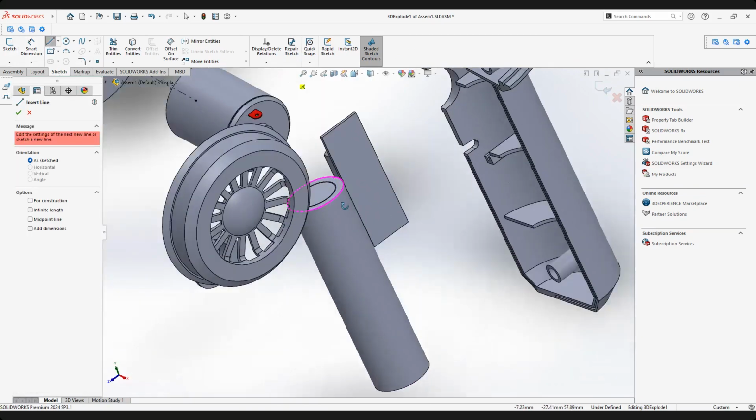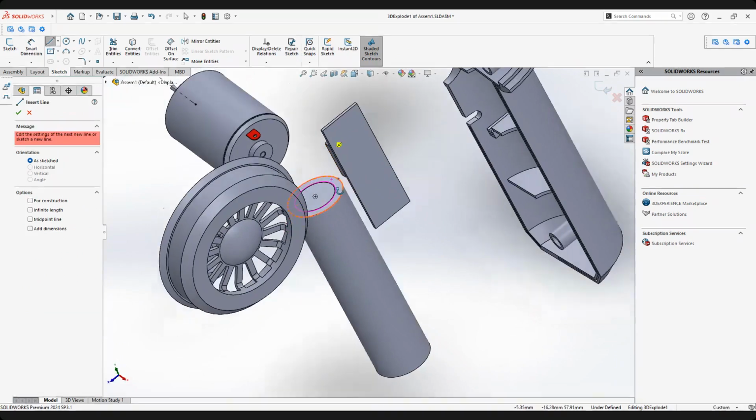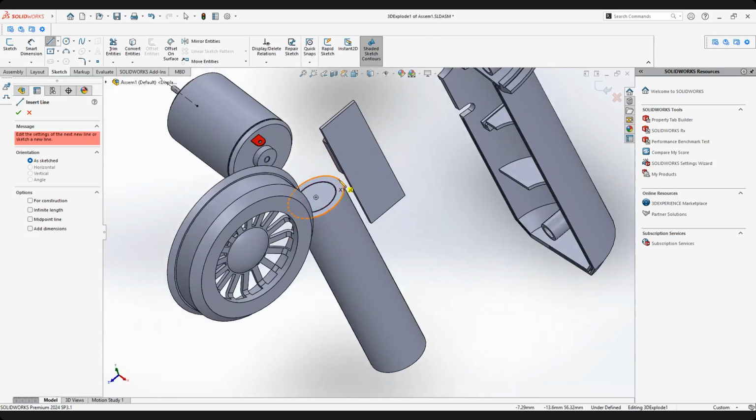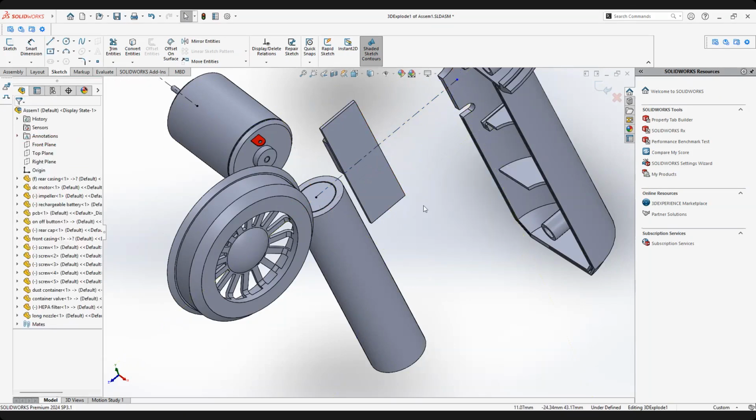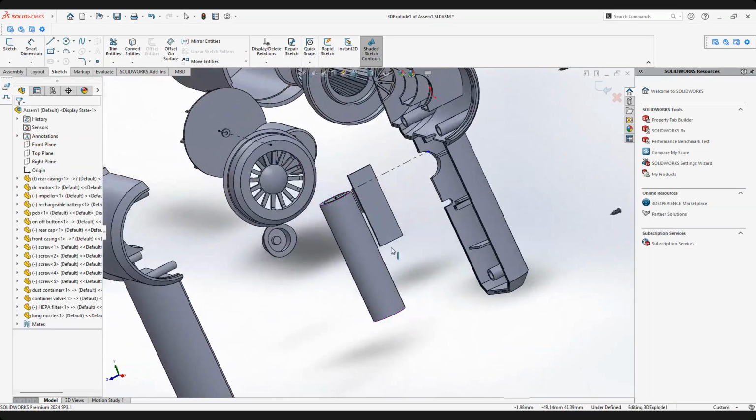All right, so I would go like this. It will go like this for this point. Because we are on XY, I'm not going for XY. I press my tab and I go for YZ direction. Make sure this is horizontal. It goes like that. We can show the path line is like that. Then I terminate. So this will be my path line.